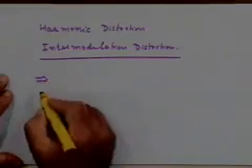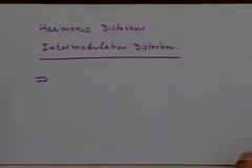And is that good or is that bad? It's very bad, right? Why is it bad? Can you appreciate? Can you suggest? Power is an issue, but it's less of an issue. It is creating components outside. Suppose you have a signal of bandwidth B. Your distorted signal will have components much beyond B, right? And obviously you are going to spill into somebody else's band.